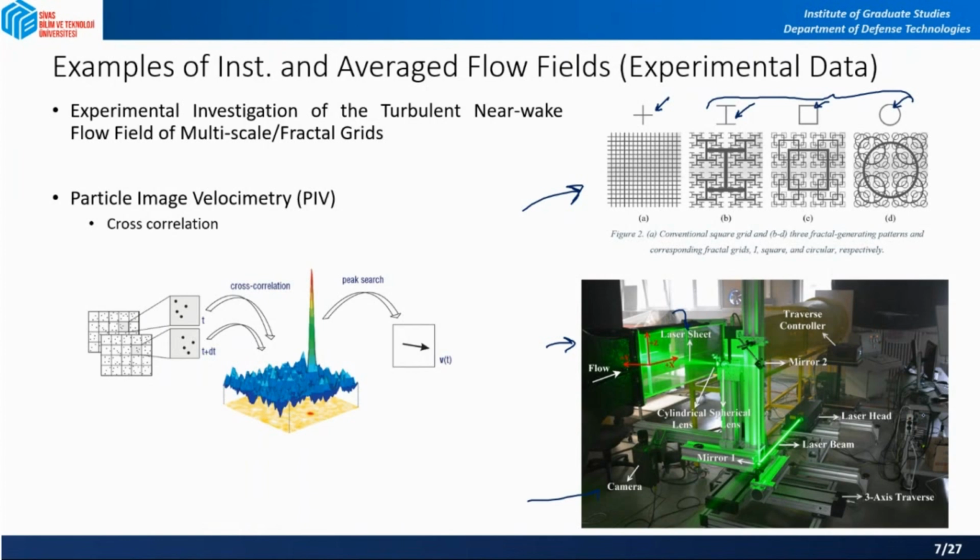Actually, while you're getting data for two-dimensional PIV, the laser sheet shouldn't be too thick, because if it is too thick, then some particles can travel within the thickness of it. And since you are taking your picture from normal to this, your camera cannot capture this movement, because it is movement in a third axis.